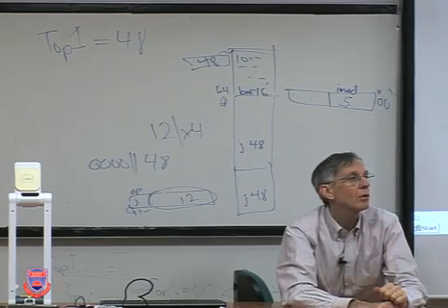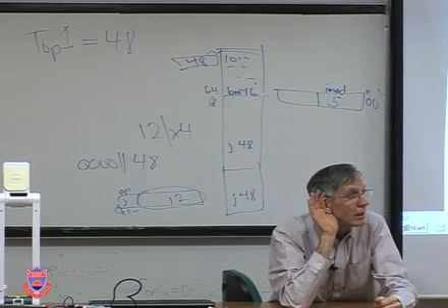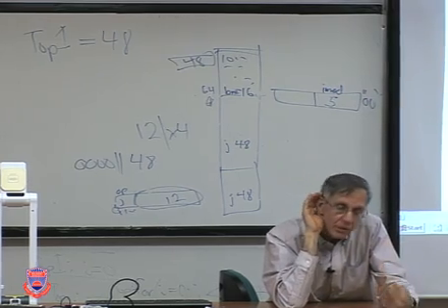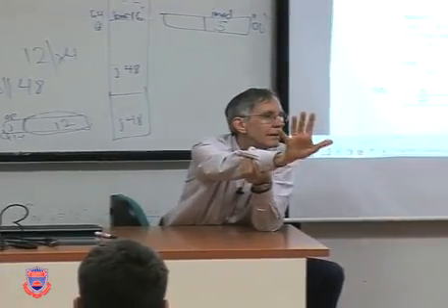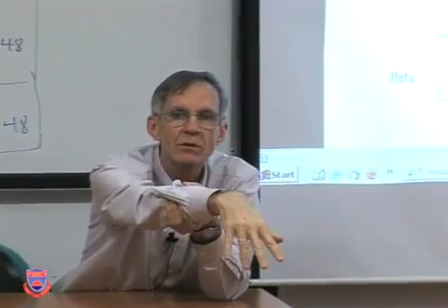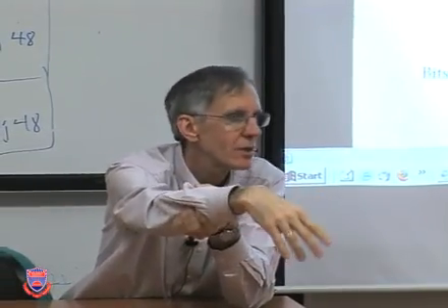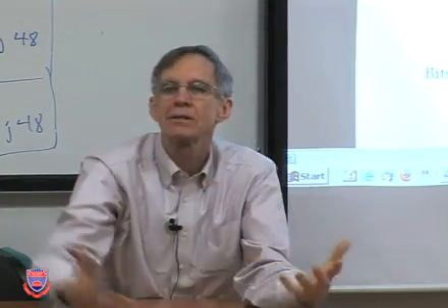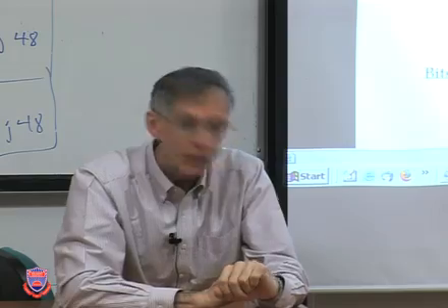We've got 2 more to go get the next instruction, and their names are PC relative if you're branching, pseudo direct if you're jumping. Only 5. That's a RISC machine for you. CISC machines will sometimes have 20, 30, or more addressing modes. Very complicated. The control to do those becomes burdensome and large and slow. All right, great question. Thank you.